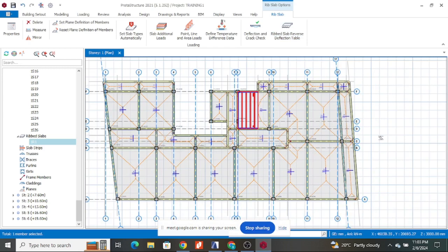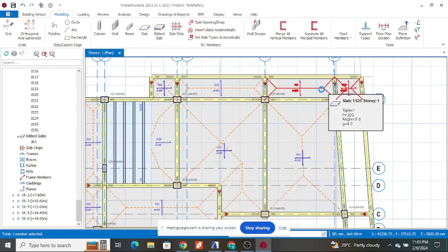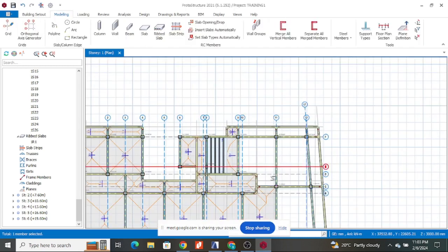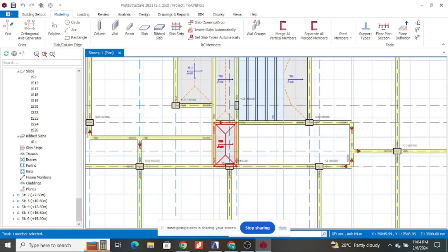So you realize we have done beams, columns, beams, and slabs. Now, for this structure, I did not model solid slabs. I was just doing this to show you. This structure, we designed it using hollow pots. Hollow blocks. Hollow and ribbed. When we see ribbed slabs, between those ribs we have blocks that are hollow. Yes, hollow blocks.